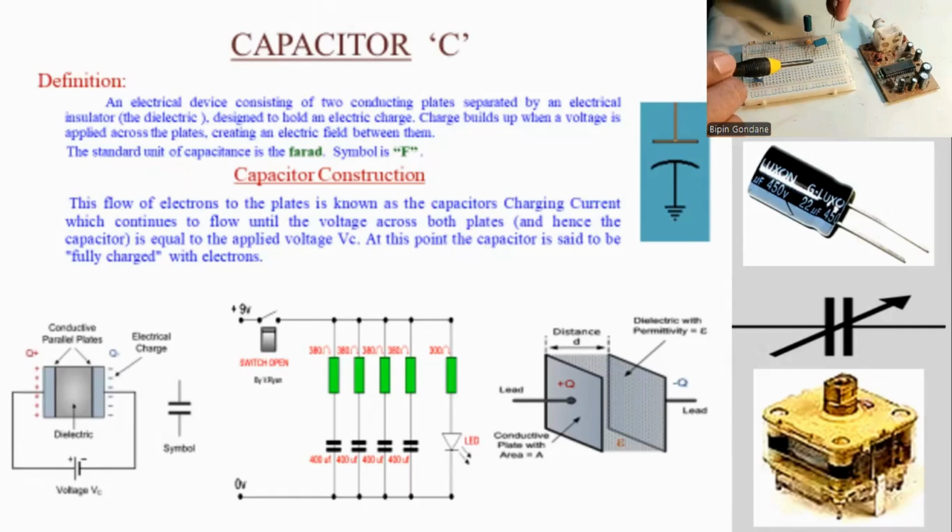So this is one of the things you have to learn. Wherever there is an indication of plus and minus, that is an electrolytic capacitor. Others are non-electrolytic capacitors. So these are all microfarad. This is also what we call the picofarad capacitor, which is here, this small disc type of capacitor. This is a picofarad capacitor. Okay, so two types of capacitors again.